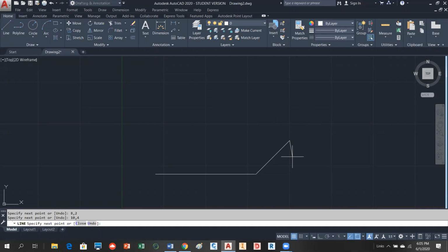Nope. Okay. So we're sitting at point C on that diagram, and we're going to go up to D, and D is 2 units above. So right now we're sitting at a coordinate of 10, 4. So we're going to stay 10 in the X. So we're going to say 10, comma, and 4 is 2 units more up. So we're going to go 4 plus 2, that'll be 6. So we're going to hit enter, and that should take us up to the top like that. Are we good?